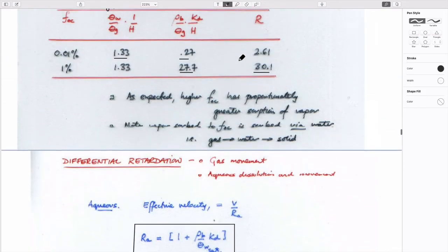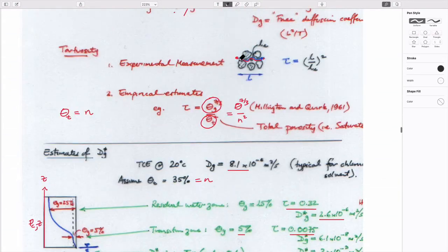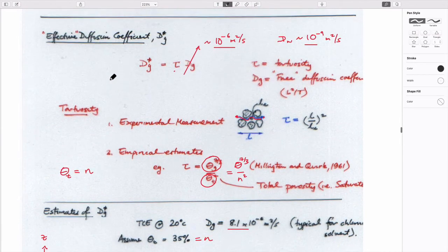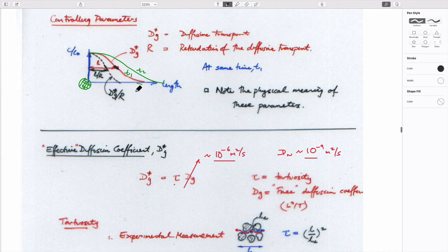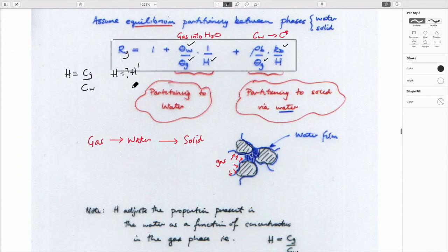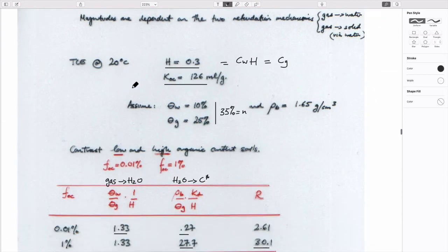And so when we looked at this, by definition what retardation meant was this idea that if it's gone 10 meters in 10 days and it's conservative, then if it has a retardation factor of 2, in 10 days it would only go 5 meters by diffusion. So we can use that length scaling to define the behavior. But also we could use that length scaling to look at the arrival times that occur at some particular location. And so the retardation factor will also determine the first arrivals in a system.